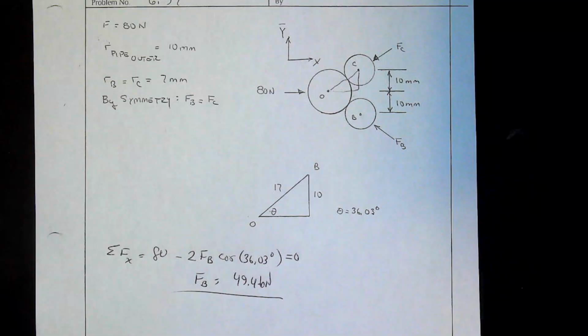Let's see, we got 2 meters here, 1 meter there. So EX is going counterclockwise. So we have EX times 3 away. All right. The Y component of FD is aligned here with C, so that does nothing. I only need the X component. So let's see, that is, and that's going to go this way, so that's clockwise, so I need a minus FD, and I'm looking for the X component, so I'll take the sine of 45, though it doesn't really matter, because you can be in this side and take the cosine.